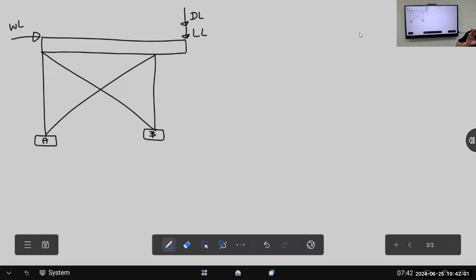The first assumption under equilibrium: we have three physical equations applied on any static system. When I said the system is under equilibrium, I mean what? All the forces in x direction, the summation of it is zero. Otherwise, if there is a value in x direction, this body will move. Then sigma y, all vertical forces, the summation should be zero. Sigma moment at any point in this system should be zero. Now this is the second assumption.